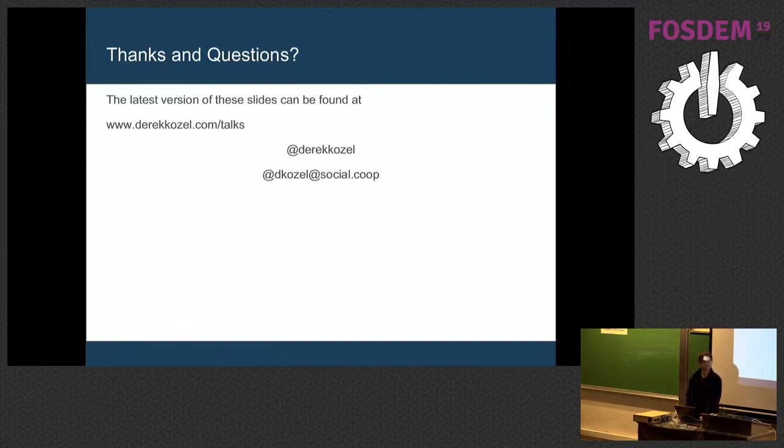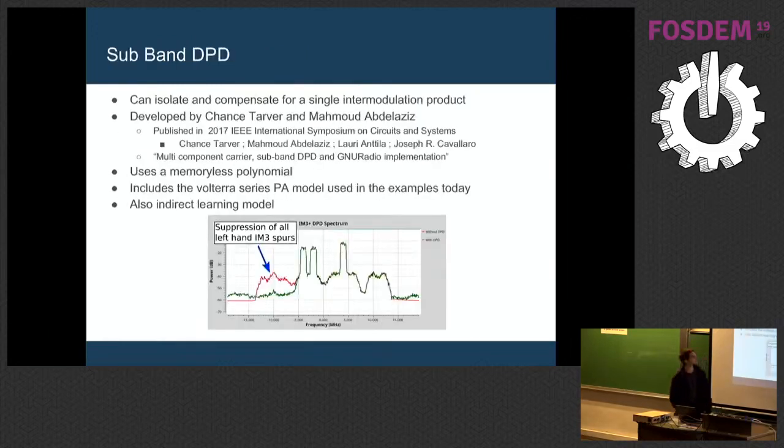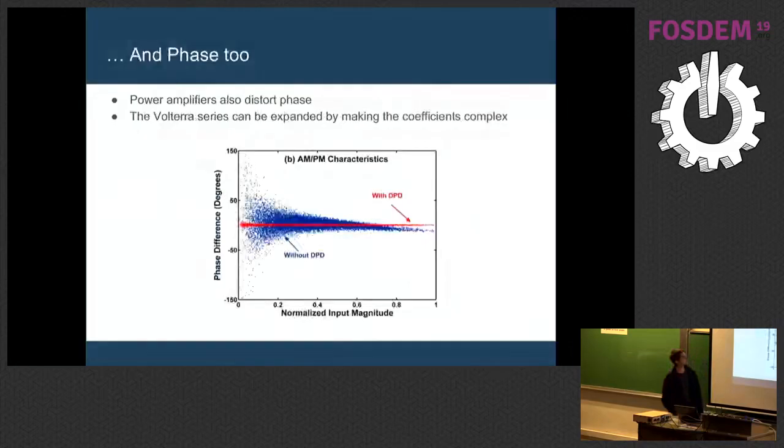You can do amplitude with the lookup table, and then you do phase. Same operation. If you have this measurement, you just have complex coefficients in the lookup table. And so instead of doing one multiply, you're doing two. It works, yeah. You get basically the same accuracy on both of them.